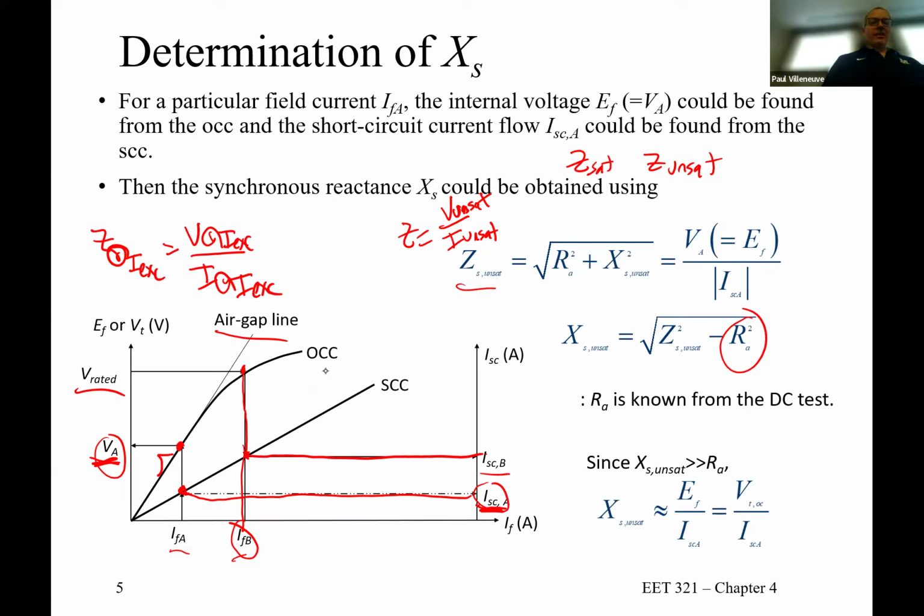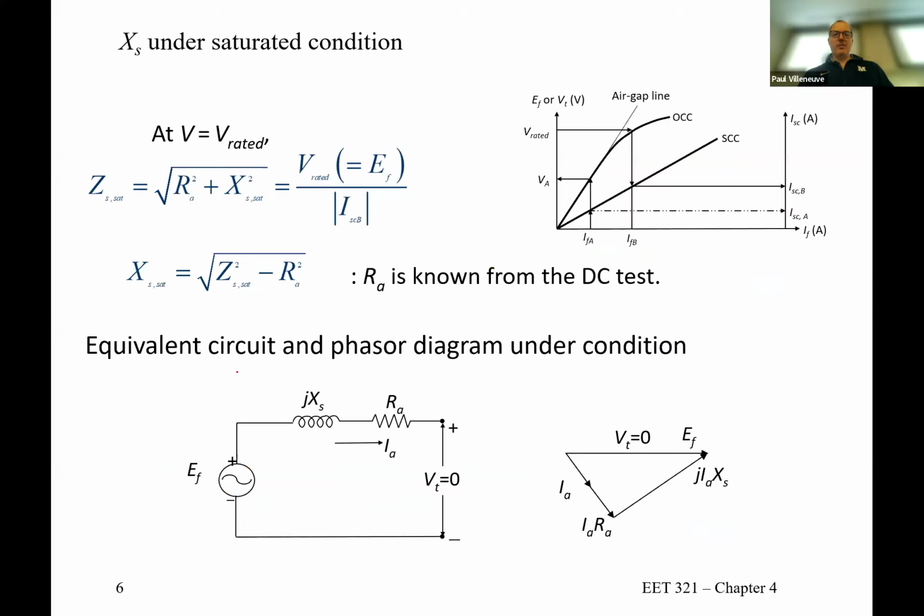Because the hard part is, when you're running these things, you're trying to calculate the impedance, and the impedance can vary. So when you're operating here, you normally just assume sort of a middle of the road number, because otherwise you have to come up with a nonlinear curve, and it makes things much more complicated. You can model it, but the problem is now you have to do a small signal analysis, or you actually have to have a lookup curve, which is, hey, my excitation current's this, this is what the voltage needs to be, so you can make it more challenging for you. Okay? That's how you're going to do some tests.